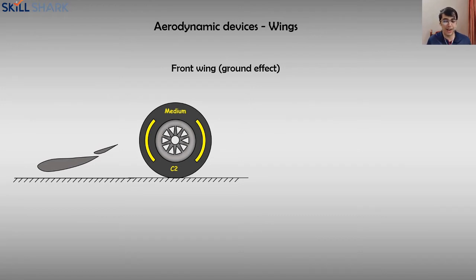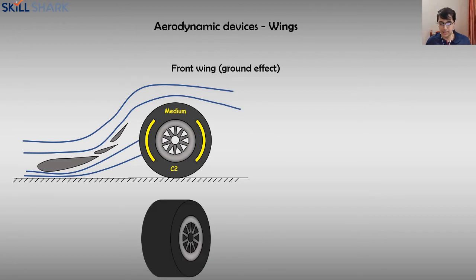So in a way, open wheels are an aerodynamicist's biggest nightmare, but in open wheel racing, that's what the definition is. So you can't get around that. The only way to get around that is by sending air around that. So one of the things that you can do is send air above the tire by adding an extra element. Obviously, rules don't always allow this, and you need to change the angle of the airfoil, not just in this plane, but from the front as well, to kind of direct air around the tires. So that's another job of the front wing. Now, another problem with these tires is the edge of the cylinder.